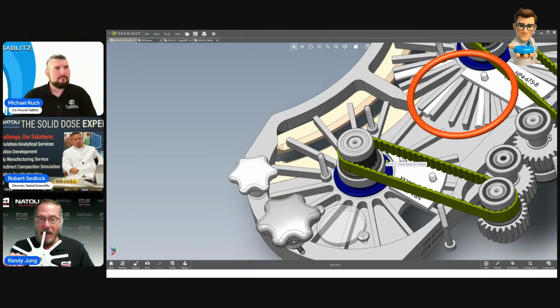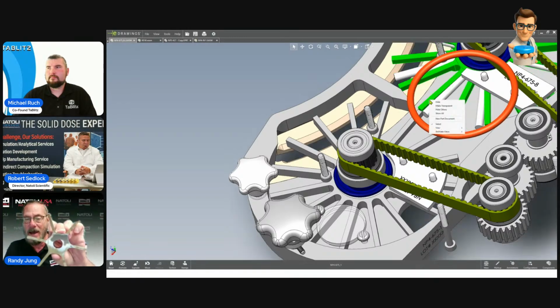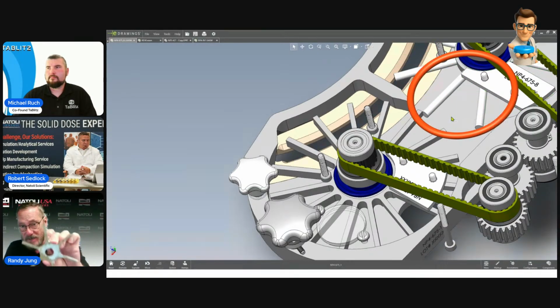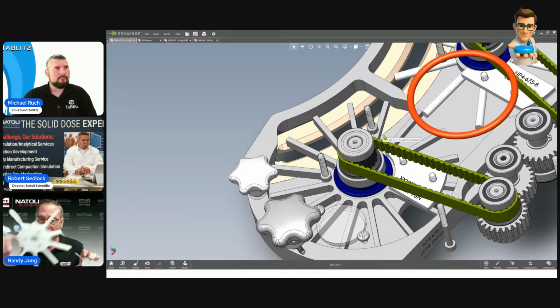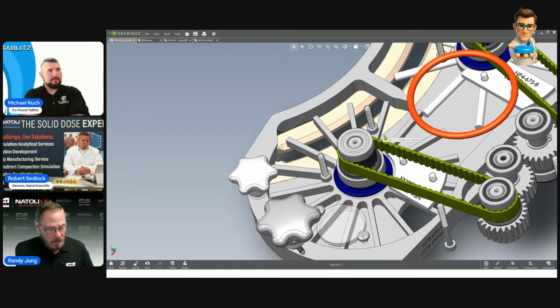So if I have a paddle, look at this paddle, it's little. This might be on your R&D machine or a smaller machine that somebody might have. The velocity this paddle is spinning at is significantly different than this one. It's almost double. So when this one's spinning at 50, this one has to spin at 100 to be at the same velocity. And a key thing is, you're measuring velocity at the tip of the paddle, right?